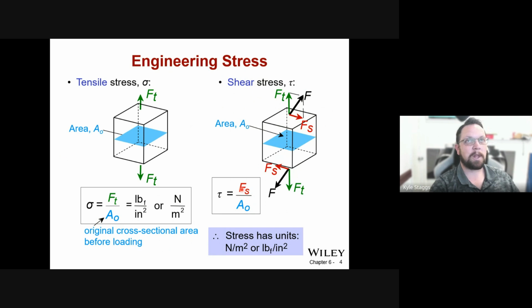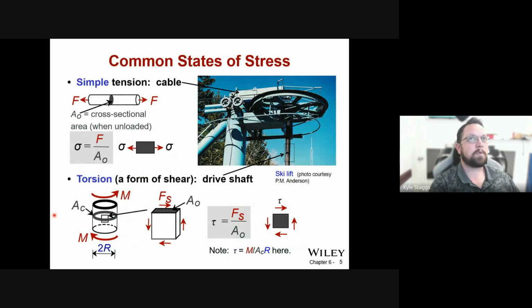As these forces are applied, the areas change. So as you begin to shear something and as it begins to move, you reduce the total area that it's shearing across. The shearing force is the same. The area decreases, meaning the overall stress goes up. Same thing here. As that area decreases, the force of tension stays the same. So the overall stress has to increase to keep it balanced. So the area shrinks, the stress increases, and this is what happens.